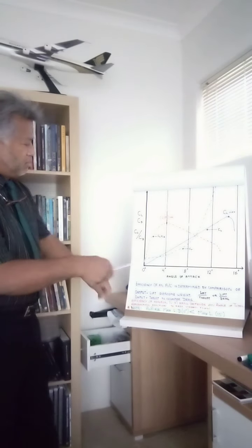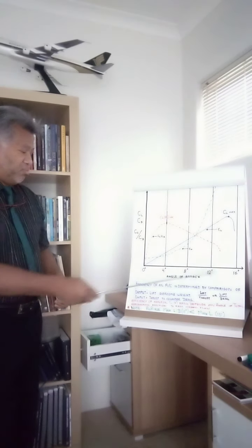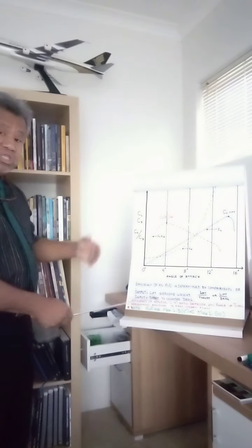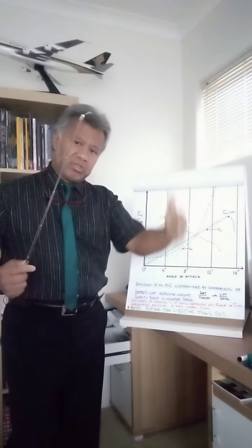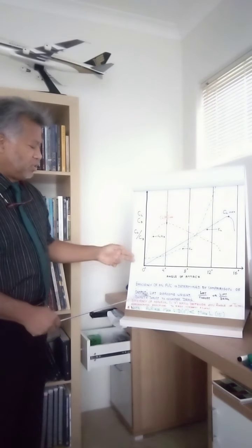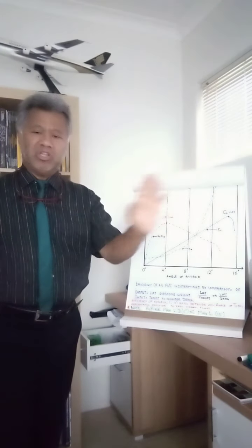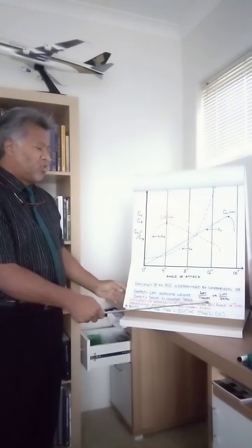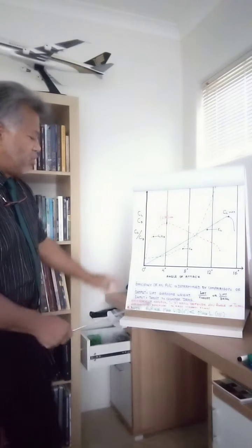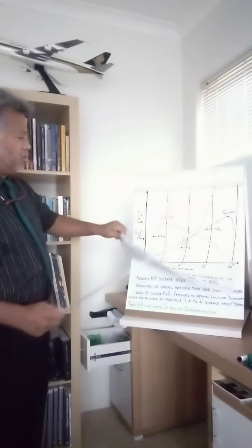So that summarizes the efficiency of an aircraft, which is determined by comparing the output, which is the lift, needed to overcome the weight of the aircraft, and the input, which is the thrust being applied to counter the drag working in opposition to the thrust. So the efficiency of the airfoil, the lift-drag ratio, depends on the angle of the total aerodynamic reaction to the free stream flow.